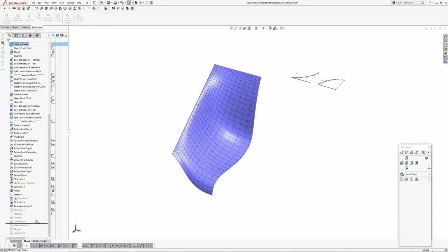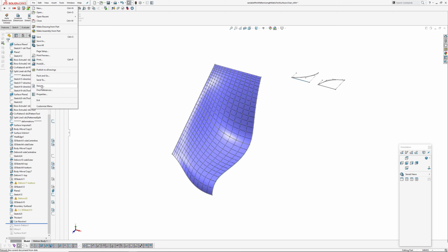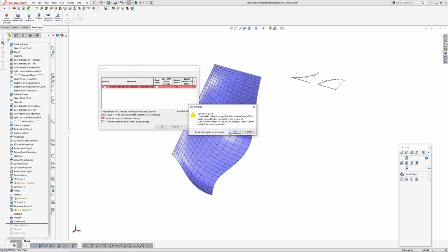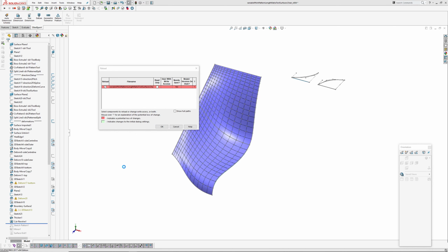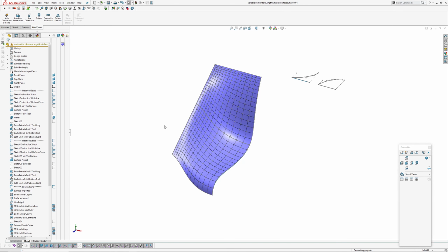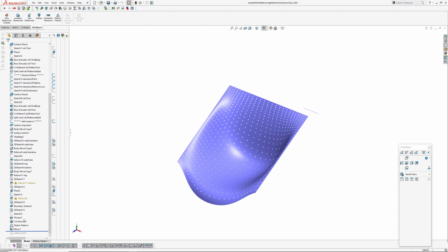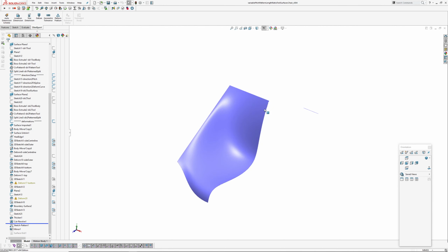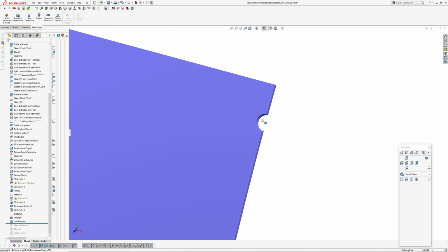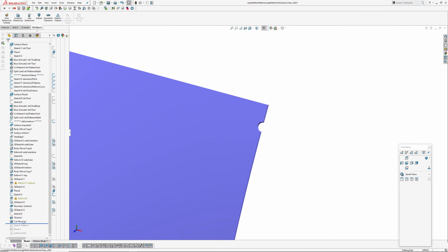Okay, so I've taken this a step further, created a, gonna reload it, a 3D sketch pattern. So I created a point at each of those vertices, and then, like in the other examples, cut revolve, just one instance of the cut revolve there, and I've got a sketch pattern.